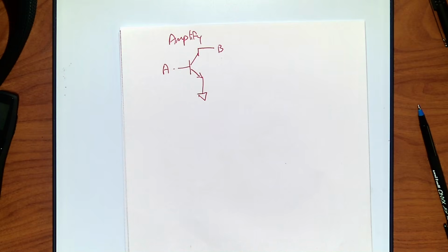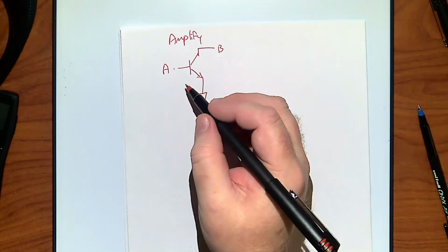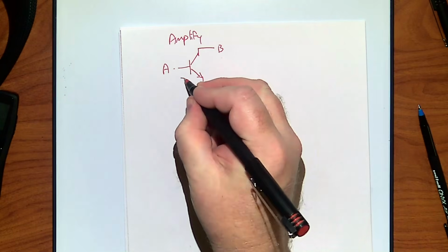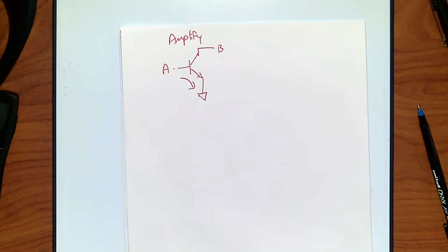All right. Now, if A goes high, say like 5 volts, what happens? It goes high. Yeah, this is going to turn on. How hard is it going to turn on? 4 volts. Yeah, 4 volts. So that's 11 volts on basically 0 resistance. So you're going to get a ludicrous amount of current, and what's going to happen? It's going to burn out. Let the magic smoke out, and it's all over with. So I've got to make sure I stop that current.